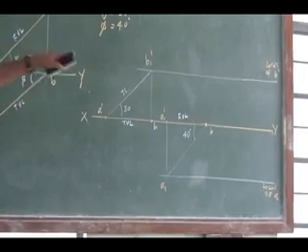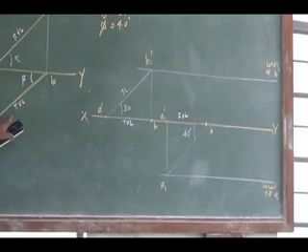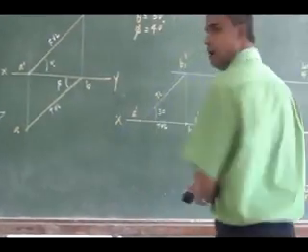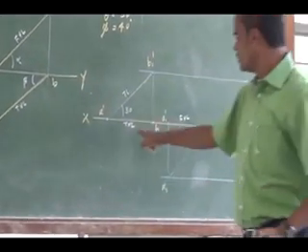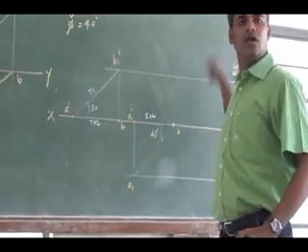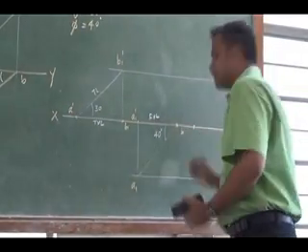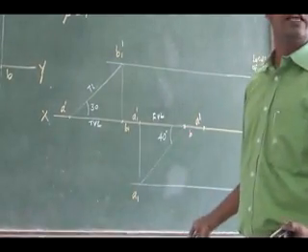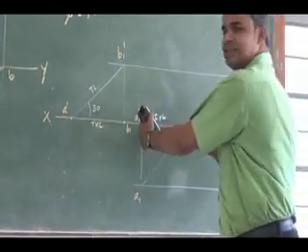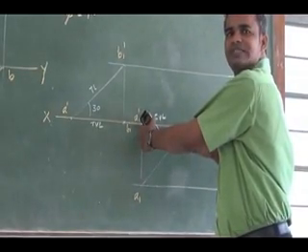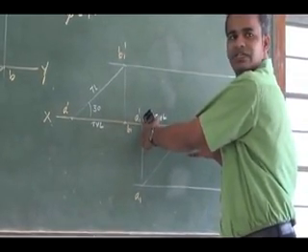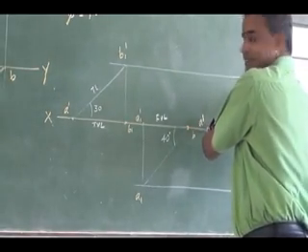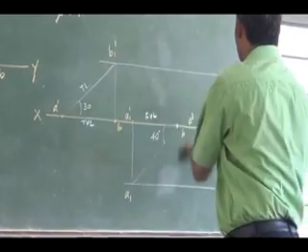And from these two steps, we have got the front view length and the top view length. So now how can I draw the final projection? I know the front view length, I know the top view length, I have got two loci. I can mark conveniently my end A dash. I can measure the front view length, which I got from the second step. From A dash I can cut it to the top locus. Right.